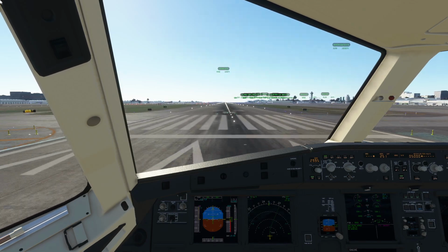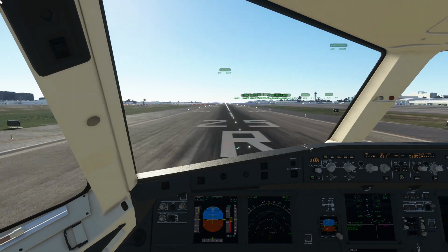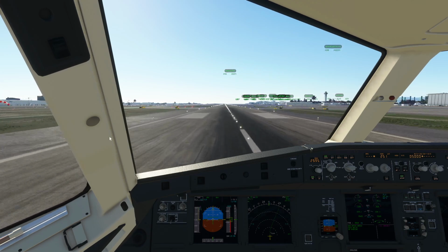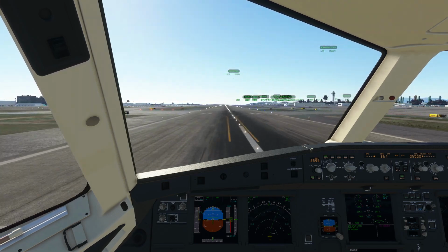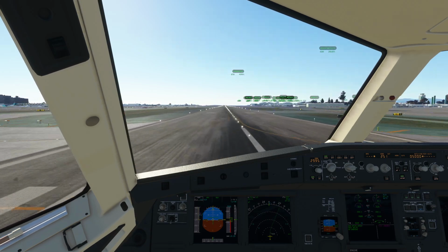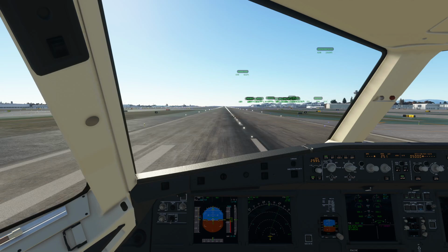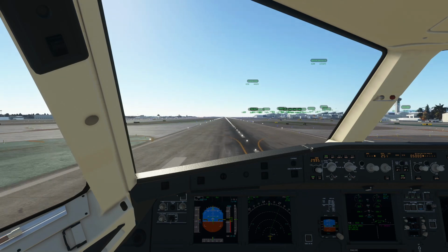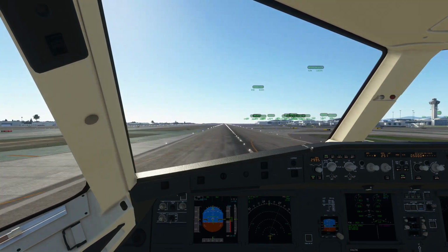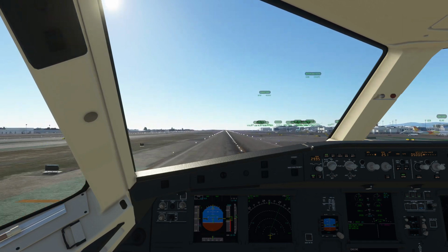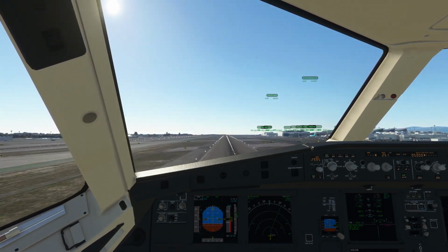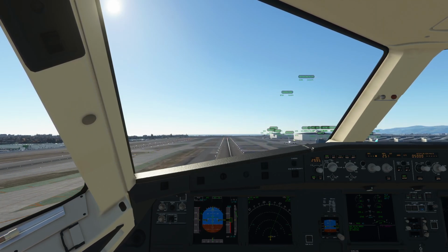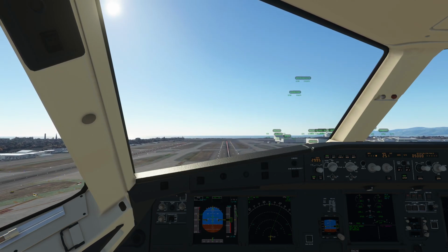Use the rudder pedals to keep yourself centered on the runway. Now, over here, we're waiting. We're almost at 140. That's when we will rotate. Remember, that's what was in our performance setting page. 140. Here we go. Once we are airborne, gear up. Gear up. There we go.